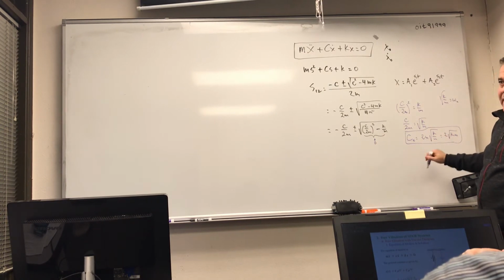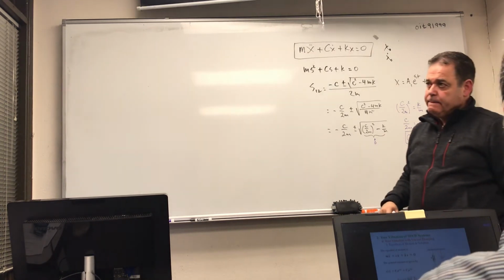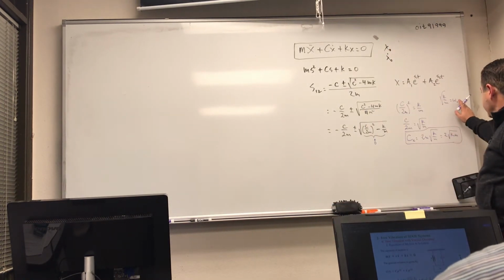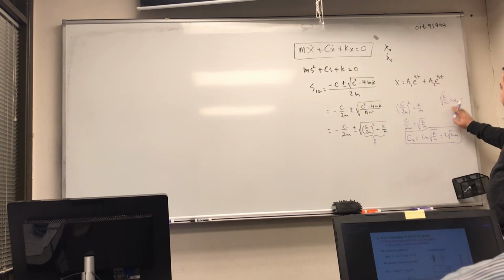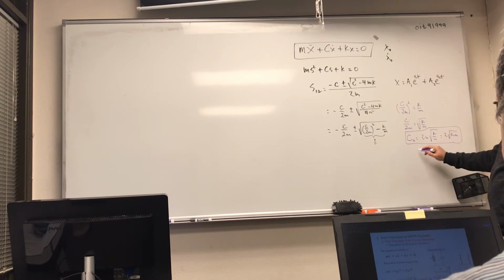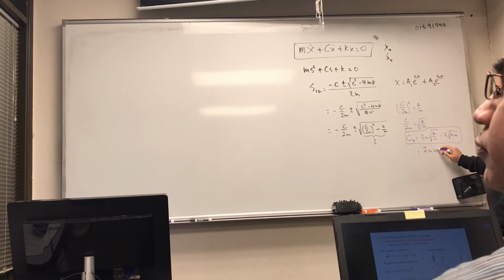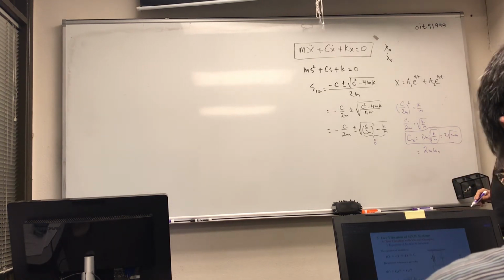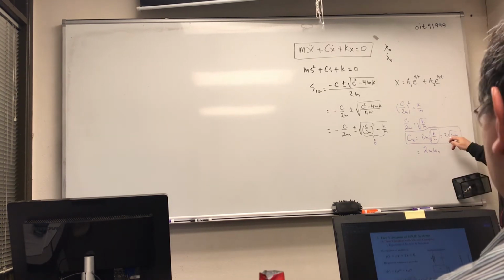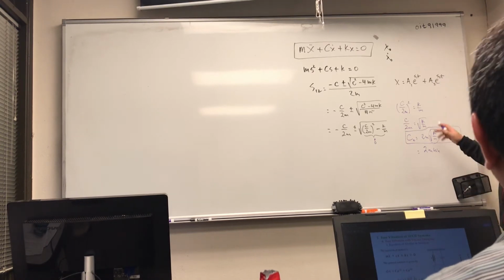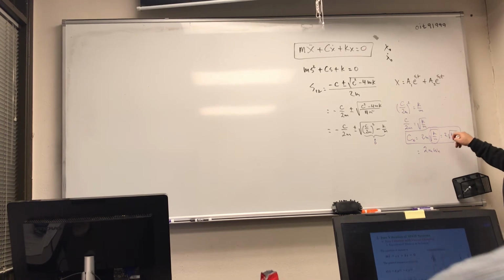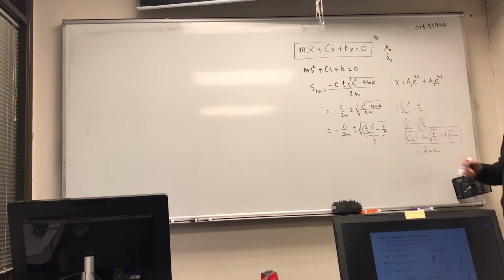But for now, how did they get that 2m omega n? They just substituted. I could have written 2m omega n here, because the square root of K over M is omega n. But the reason I wrote it the other way is that in most cases you are given a spring and the mass, so you can immediately find Cc instead of calculating it through omega n. I mean, that's just my preference.